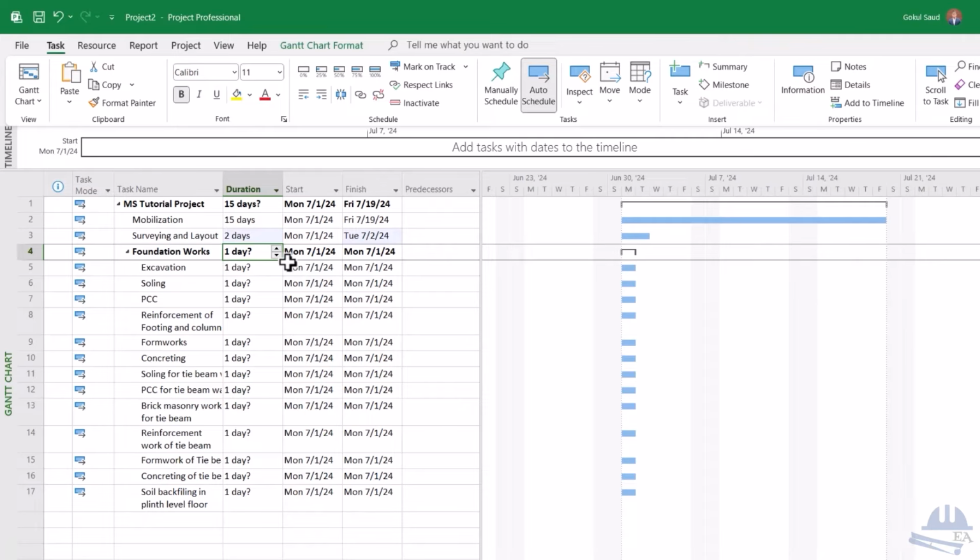And once the surveying and layout is done, you can then lay out the foundations as well to see if there are any discrepancies. If the foundations are overlapping at the site, it might happen sometime. Or if some foundation is going over the hill, or if any footing is going out of the project boundary line, these things you can see. And you also have to see if the drawings are correct or not, the outline of the project land is correct or not, if it fits as shown in the drawing or not.